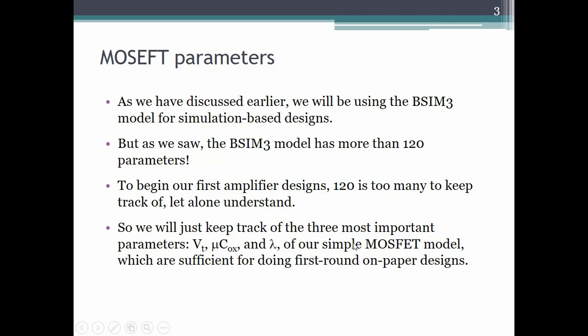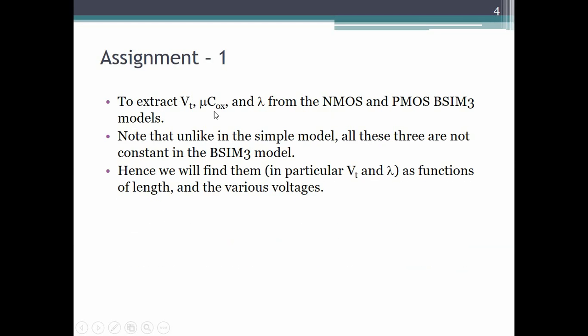First you will do that, then you will put that designed circuit in SPICE, and then you will tweak it and modify it, because in SPICE, of course, you will use BSIM3, and those results will of course not be the same as the simple model results. So the purpose of this first assignment is to know the Vt, mu Cox, and lambda for the NMOS and the PMOS for those BSIM3 models which you are going to use.